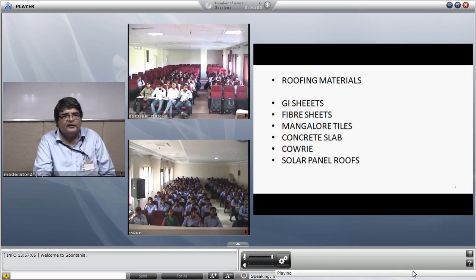They were amazed that the sloping roofs in Mangalore, where there is very heavy rainfall, were without leakage. No water leaks inside, and simply without mortar or anything, the tiles are put one over the other, and due to self-weight only, the tiles can stay in place even in high wind, and they can resist the leakage of the water.